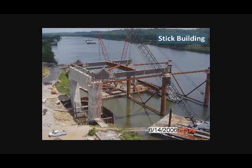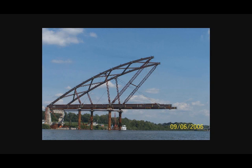We got the pier up, we got the end floor beam up. You see the shoring system or the falsework system. Pieces of tie girders are up, and you see the threatening barge in the background, where I spent many sleepless nights wondering what happens if one of those hits the shoring system, which they never did. These are 3/4 inch steel casings. They were filled with sand for a little bit of protection, but the contractor told me the main protection is good insurance. And then we're moving on to the next stage.